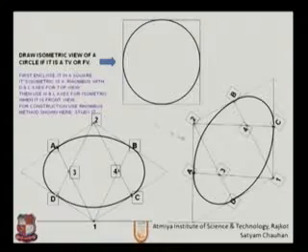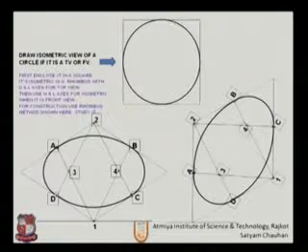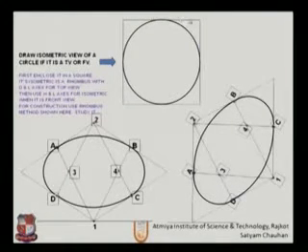So again, if I repeat, first inscribe the circle with a square, measure the length of the square, and draw a rhombus required to draw the isometric views. For the top view, a rhombus, and then an oblong to produce the front view.